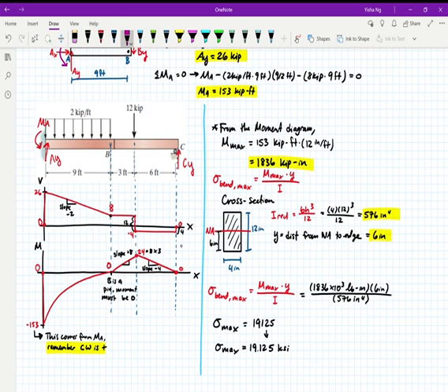In this case, my value 8 is above the x-axis, is positive. So I know that because my shear force is positive 8, my slope in my moment is going to be positive 8. So I'm going to increase until here, which is where the positive 8 ends. And I can figure out the change by taking the area under the curve. So I can calculate 8 times the 3 feet that it acts on. 8 times 3 is 24. So I know that my moment here at the end of that increase is 24.